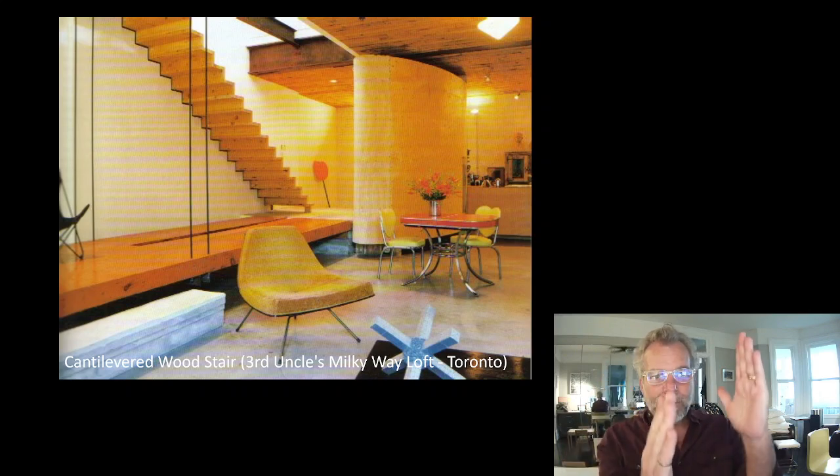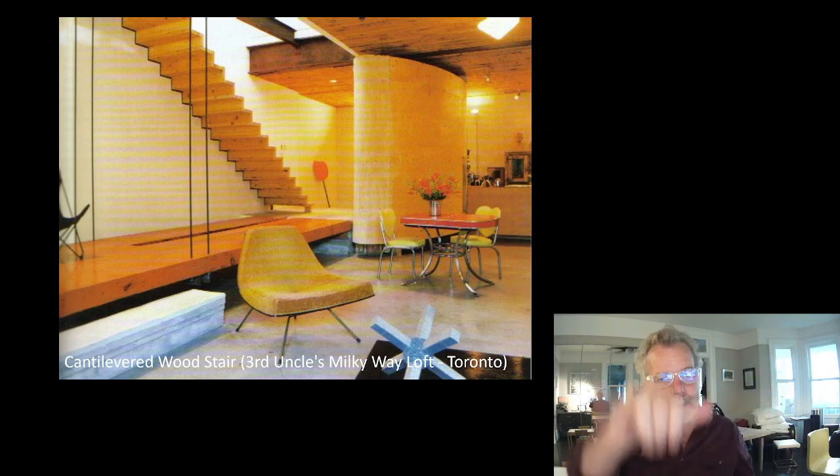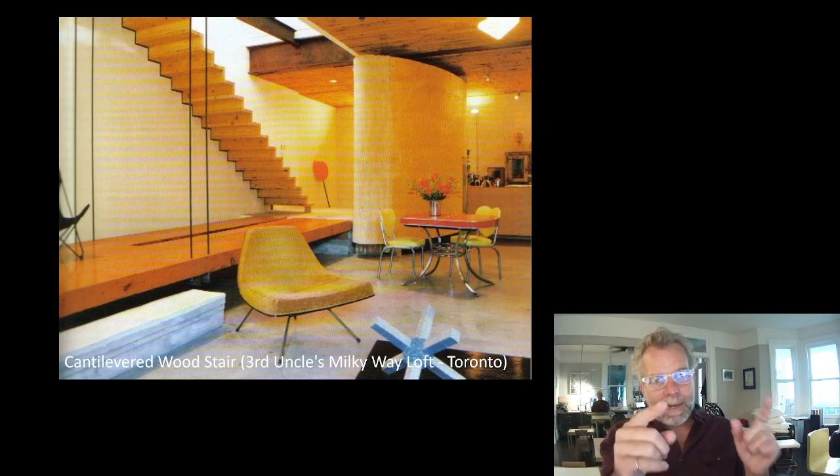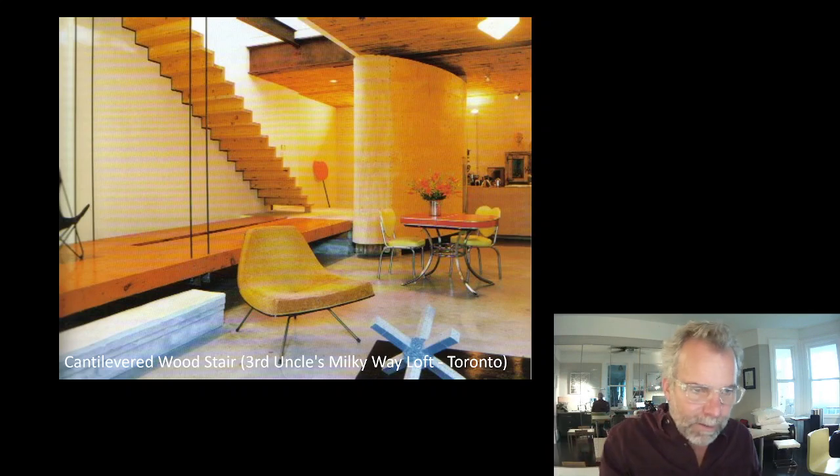Our lever arm is maybe a foot, which means that we're going to see a rotation in that tread, if we were using normal lumber, of something like 1/8 of an inch in a foot, which translates into 3/4 of an inch. No, not 3/4 of an inch, but 1/2 an inch by the time we get to the tip of the tread.